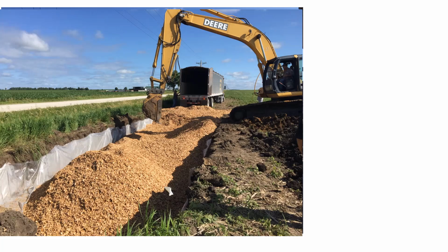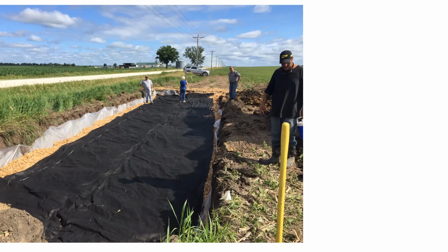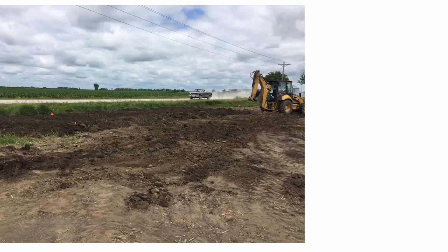Generally, you're not going to actually fill up 3 feet of water within the bed of the bioreactor bed. So if you are starting to run short, maybe try to get by going a little bit shallower on that outlet side. Next, you cover it up with a geotextile fabric. That really just keeps soil from moving down into the wood chips if you utilize the soil cap. Not every state utilizes the soil cap.